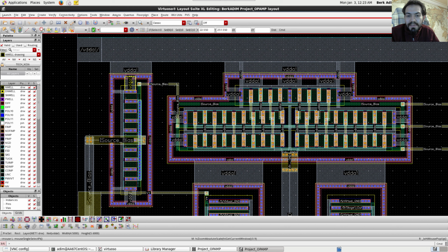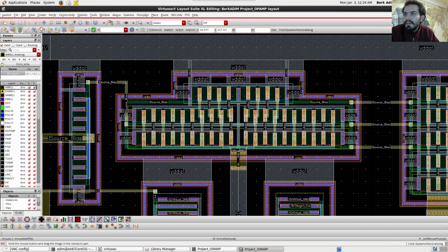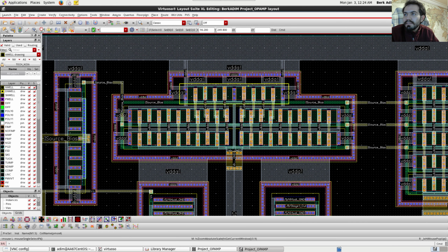The transistors with higher widths will have higher currents, and if they have the same resistance at their source, in our case we are using PMOSes, so they will have lower source voltage, which is not something we desire. So we must adjust our resistors accordingly. So as you can see here, for this biasing circuit, the one with the smallest width, we have just one connection. Here we have actually three larger connections. This has 5 times the width of this. And we have the side connections here, which actually don't do much because they are limited by these connections here.